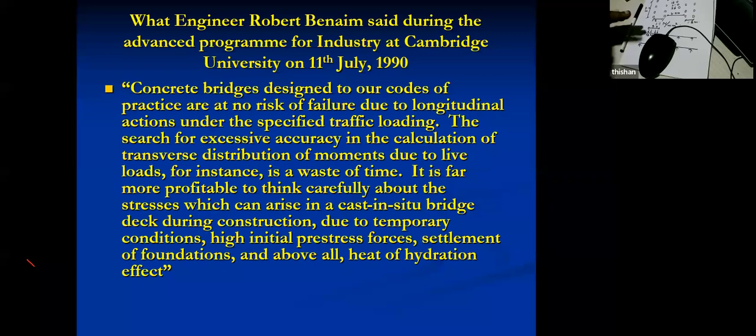On the other hand, there are some other engineers who spend hours in front of the computer just to find the maximum bending moment. So basically, if you look at this statement, you can clearly see that if you start with a reasonably accurate bending moment, shear force and torsional moment, determined by using a reasonably accurate analysis, then you are through. You don't have to worry too much about the actual maximum values of shear force and bending moment, because there will be adequate factor of safety.